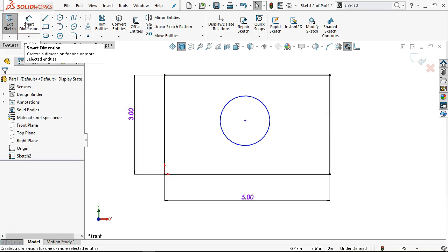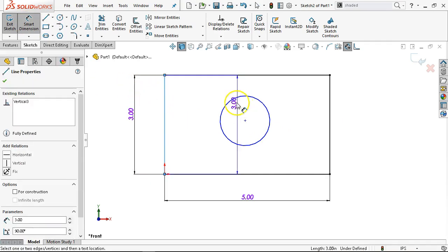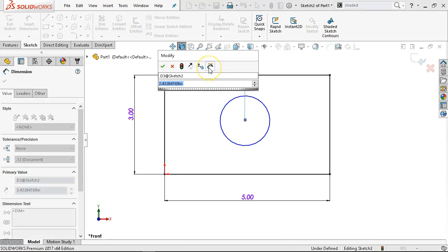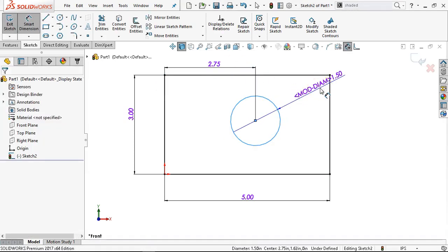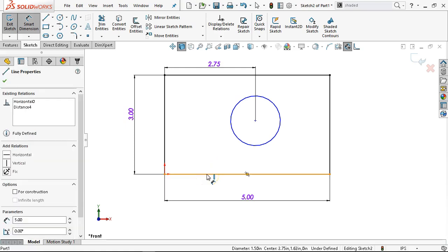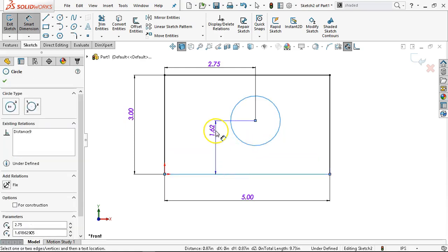All right, so to review from Tuesday, if I place a dimension, and we were at 2.75, and so dimensions on the circle. There again, I start into dimensioning, don't even think about it. So I'm going from an object to an object. And with circles, if you're used to AutoCAD, Autodesk products, they kind of point you towards the center points. We're going to go to the perimeters. We're going to go to the outside of the circle. And there's a very important reason for that.